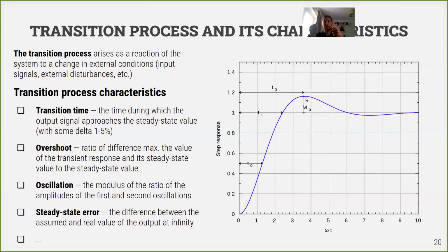Imagine we have a steering wheel in our car, and we want to turn it on a maximum angle, but with our control system here, we would turn it a bit more than a maximum angle. And in practice, it means that we would really apply huge force to our steering wheel, pushing it forward after the maximum turning. And of course, it can lead to physical destruction of the system. So sometimes this overshoot can lead to physical destruction of our motor, of our steering wheel, or any object we are controlling. This is why this is really dangerous to overshoot, and in practice we try not